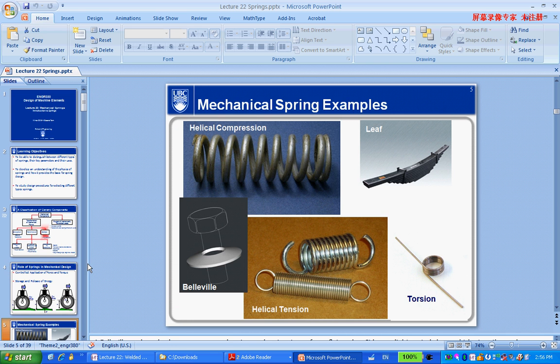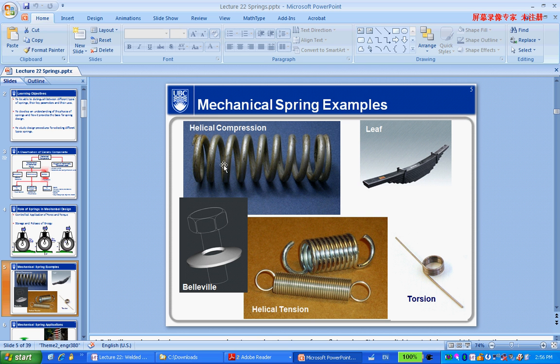There are different kinds of spring. Okay. The most commonly seen spring, this one here, is called a helical compression spring. Basically, that spring should be used only in a compressive situation, right? You don't use the helical compression spring in a tension situation. But this one is the helical tension spring, so you use that in a tension situation, right? Yeah. And this is a torsional spring. If you have pins or snap things, like the magnet on the refrigerator, you see that in the mechanism there.